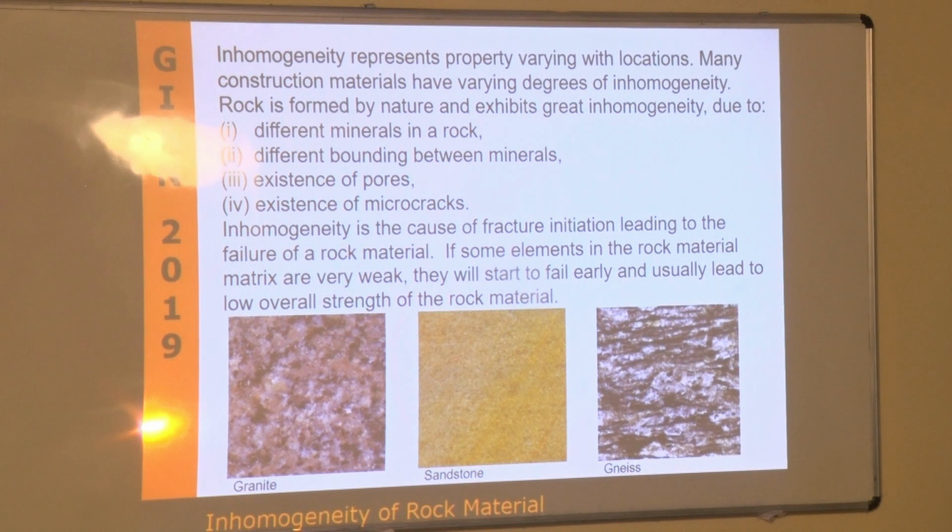So far we've been sort of assuming that it was homogeneous and continuum, but the reality is not. So we're using assumptions like Examine 2D does, a homogeneous linear elastic material. That will give us a very quick first guess or idea of what is going to happen. But the reality is that the rock will behave a little bit differently, sometimes drastically differently, with respect to those simple models.